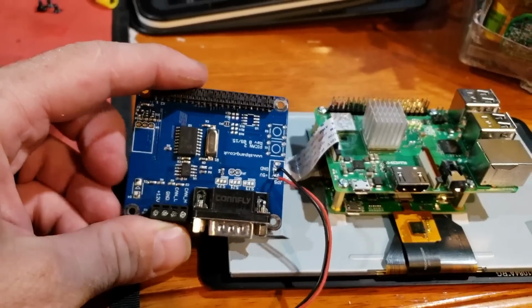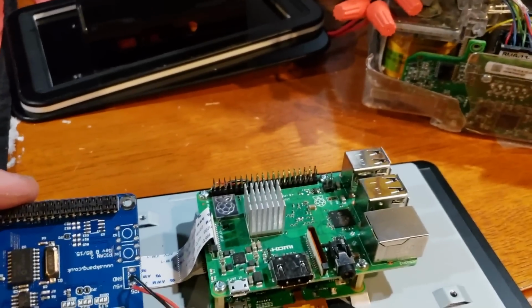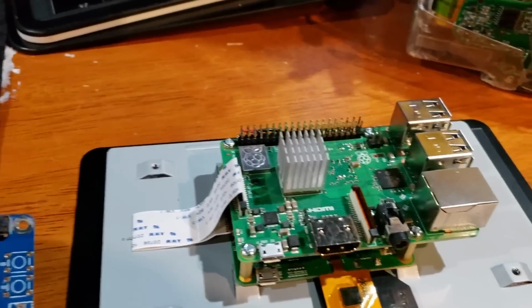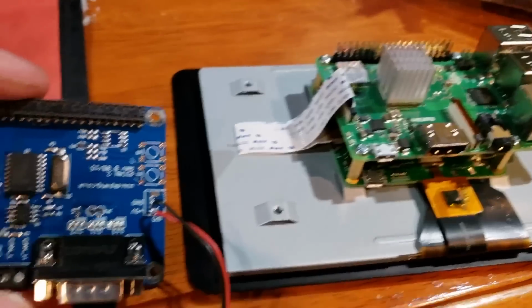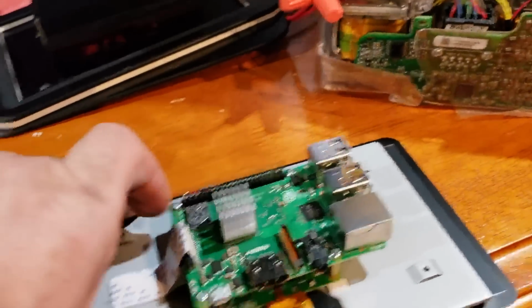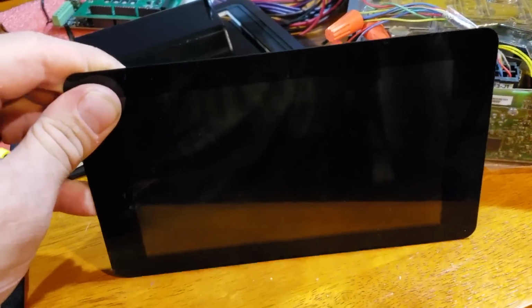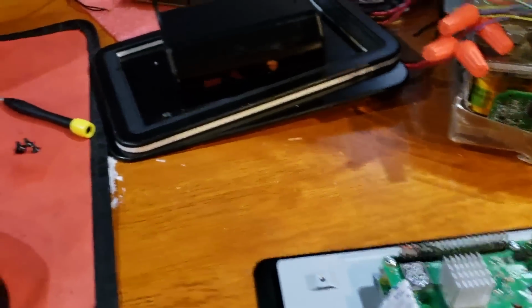The reason you might want to use the CAN shield would be for a little bit better reliability. The UDP loses frames sometimes. It's not a big deal because it's sending so rapidly that you'll get one in a few milliseconds anyway, even if you miss one. But with a CAN shield, you could put your display much farther away, say even 1,000 feet away from your battery packs. You could put this in your house even if things were separated by quite a distance. With a CAN shield or a CAN hat here, you could hook everything up still and you'd get reliable performance.